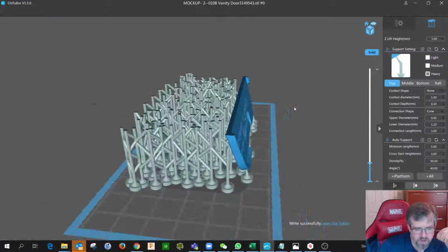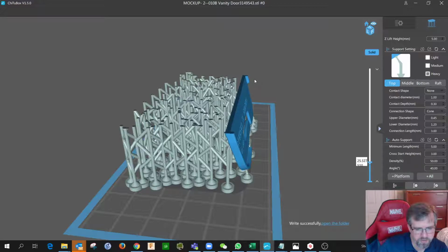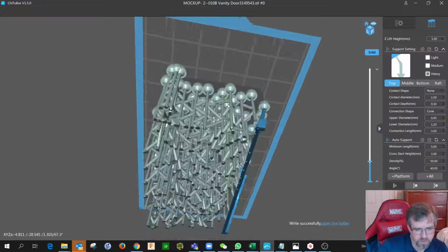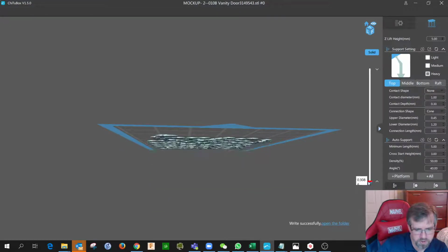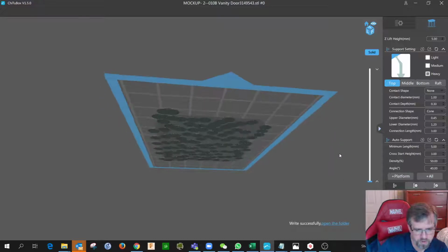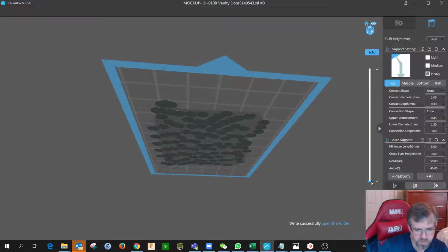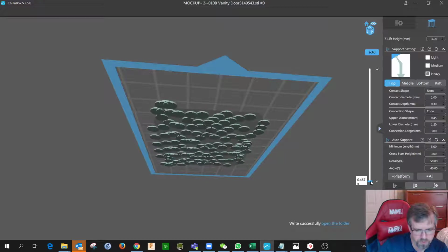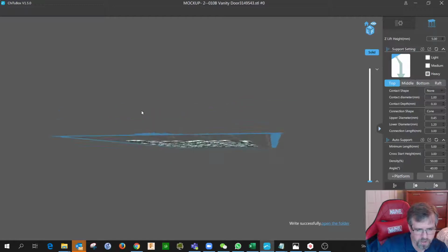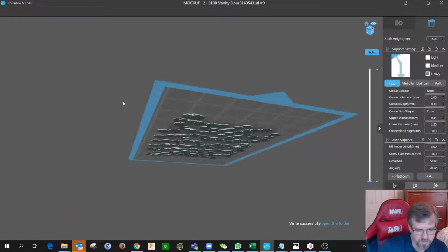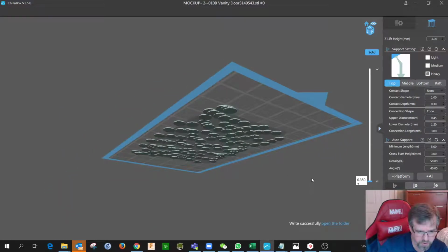Now again, try to keep that in your mind, that as this is printing, it's not coming up from the bottom, it's coming down from the top. So the very first image is going to look like that. That's what's going to be attached to your build plate, and those first 5 layers are going to have that 60-second cure time. So everything up to here has a really tough cure, so it's going to have a really good attachment, hopefully, to our build plate.